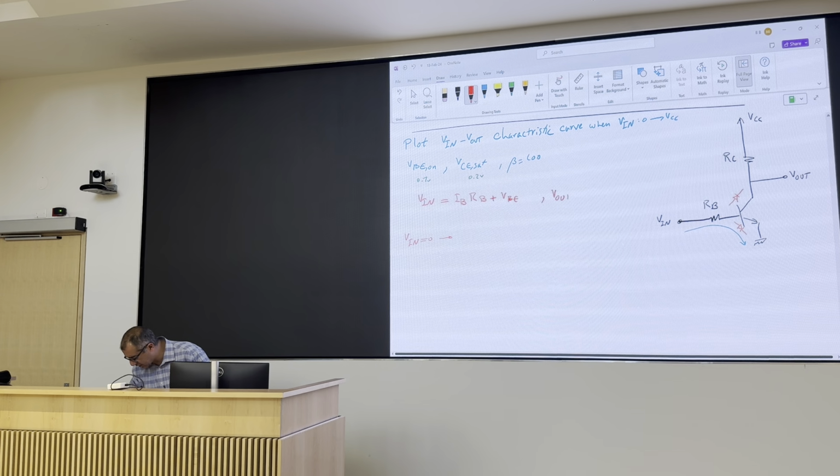So let's say a reasonable value for RC. This diode, the VBC diode, will remain reverse biased, right? So if you have, let's say, 0.7 here and 10 volts up there, maybe it is 9, maybe it is 8, maybe it is 7, but it stays off, right? So you'll be in active region. Okay. So after off, you enter active region, meaning that BE is on and BC is off.